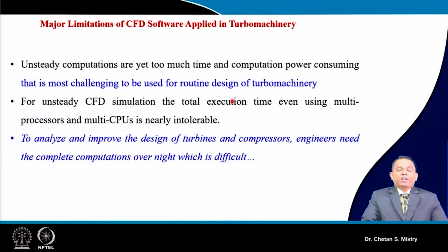Unsteady simulation is a time consuming affair, as we have discussed, so we cannot do it for the initial designing stage. Initially, when we are doing our design, we go with steady simulations. When we go for a detailed performance assessment, only then do we look for unsteady simulations.